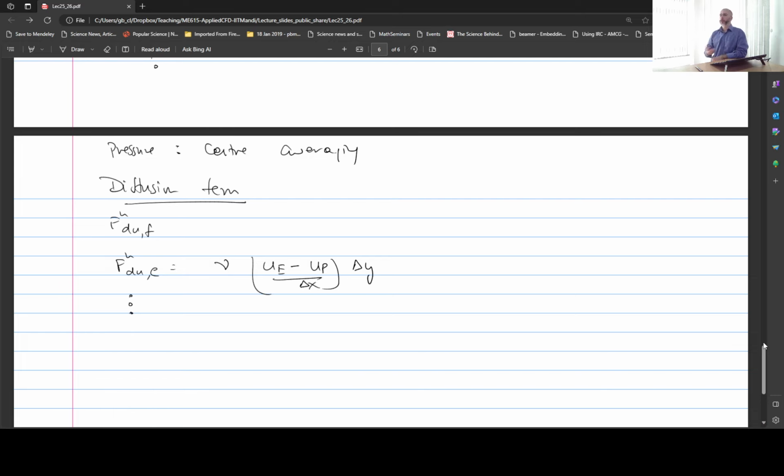Well, in a course like this, it's convenient to use structured grids. Structure means that you have some sort of structure. So if I give you some size of delta x and delta y, and some way how the delta x changes with x and delta y changes with y, you can generate a whole grid. I don't need to store the coordinates of each and every point in a file. There is a structure associated with the mesh or grid.